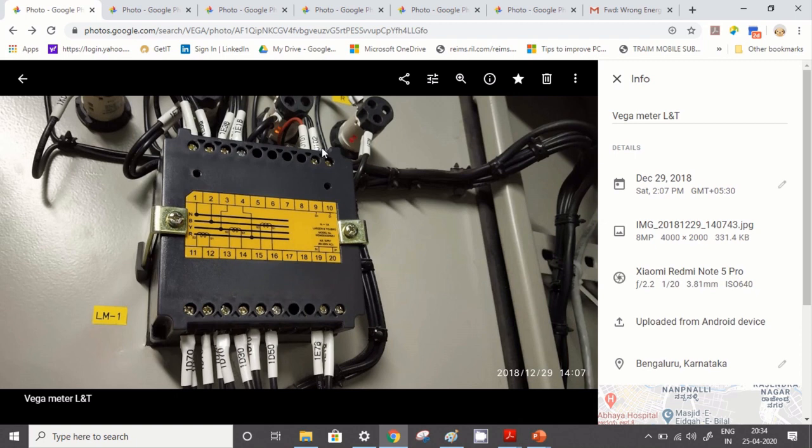these two terminals J101 and J102 come out, which we can see as red and black. Similarly in the DG section the same terminals come out, and they are connected in parallel, red to red and black to black, and from there it becomes common and goes to the SMPS. I will discuss that diagram from the LT panel to the SMPS connection also. So this is a very important thing.